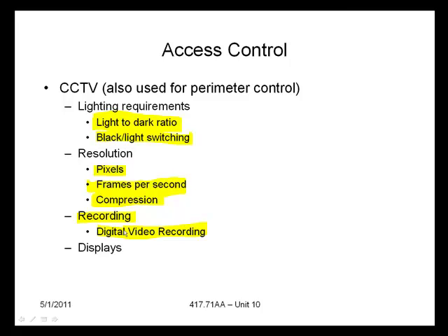Digital video recorders have self-contained burners for storing the data. Most security specifications require they be able to store a minimum of 45 days of camera image. The amount of storage depends on pixels, frames per second, and compression. So you need to consider your storage and archival requirements when you're looking at recording equipment as well. Displays: you can have a single image display which just shows the image the camera sees, a split screen where you see multiple camera images on one monitor, and large format displays for showing several camera images as well.